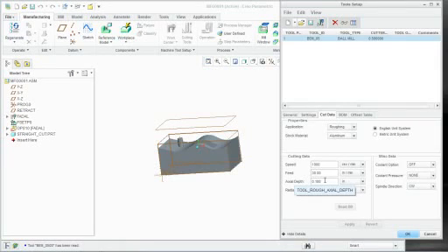Now, if I have multiple materials that I am using, I can fill this information out against multiple materials. And whatever the material is that I have selected in my operation, it will automatically adjust to whatever I have saved for that time. Okay, so if you fill this out one time, if you go back in again and you start something fresh and brand new, when you start your operation and you say I'm going to have aluminum, when you go in to pick your tool, you will automatically have this information filled out.